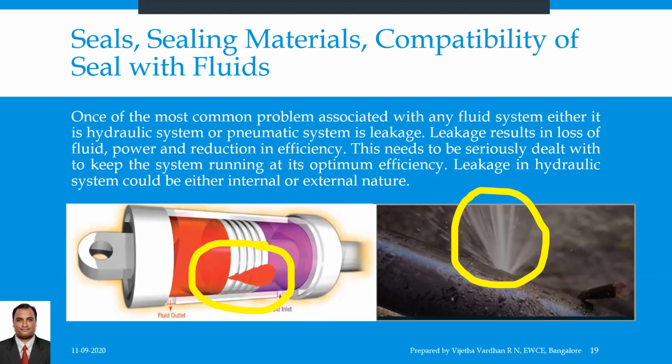External leakage is unsightly and can be hazardous. This leakage is due to improper installation. Leakage through joints may be due to shock or vibration, which will loosen them. Failure to connect the drain lines, excessive operating pressure, and contamination in the fluid are some of the common reasons for external leakage. External leakage leads to the loss of fluid, which will increase the cost of operation of the hydraulic system. Thus, leakage can be prevented effectively by using proper seals with the correct specification and application.